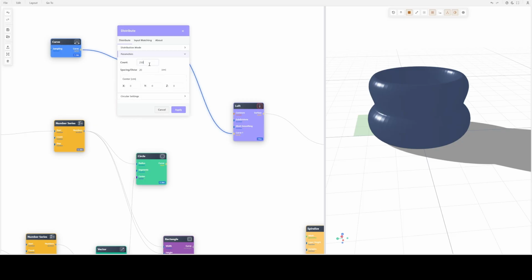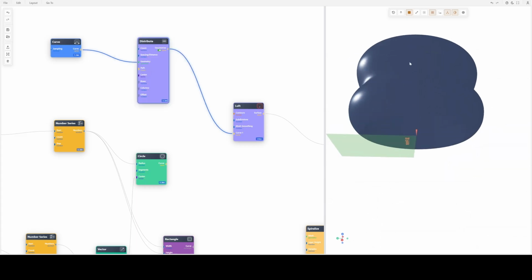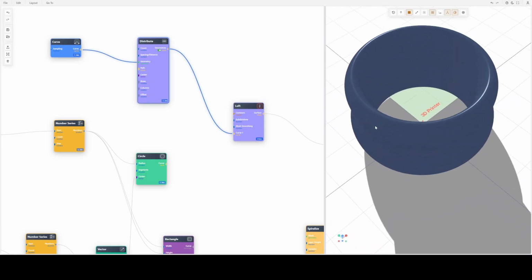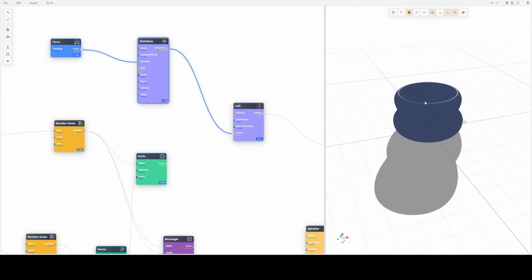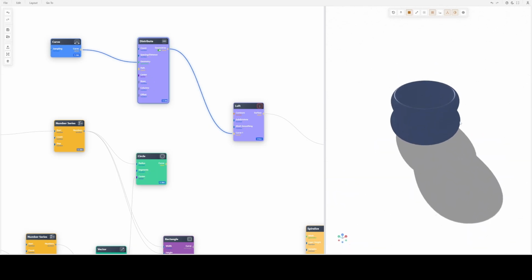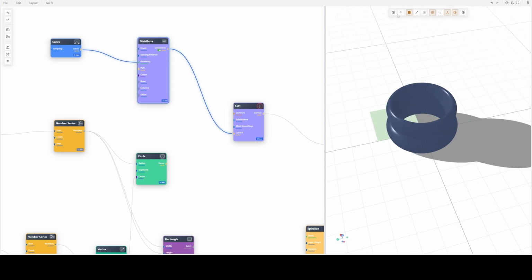So, and we will increase the smoothness much larger here, and I think for 3D printing, it's actually smooth enough. And yeah, this is a different kind of loft. I am not even sure if it's also called loft in other programs, but for me it's still a loft.